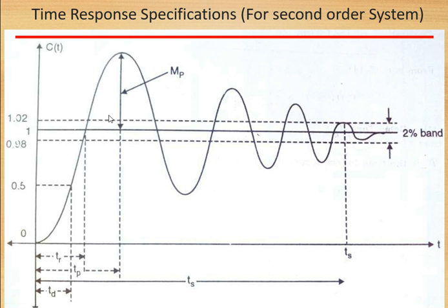So here this is also called overshoot, this is also called overshoot, and this is also called overshoot. But out of these 3 or 4, which is maximum? So this is the maximum. So how to calculate the amplitude of this maximum overshoot? Just measure it from unity to the peak value, or this highest value. So this is the amplitude of a maximum overshoot.